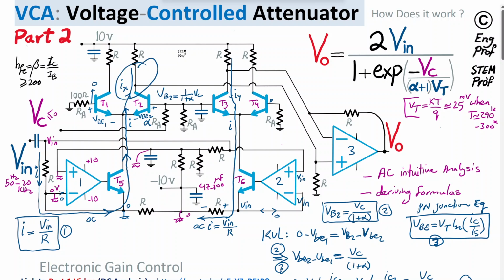We found Ix now, the steered current toward the target branch, in this case toward the right branch of the differential pair shown here. We just want to see how this translates to Vout, or how this affects Vout. Okay, so let's focus on the connection. This Ix, what is it seeing AC-wise? There is a bypass cap here, let's say 47 microfarad to 100 microfarad range, so that for the frequency range of interest, that is effectively a short. So it provides a virtual AC ground here.